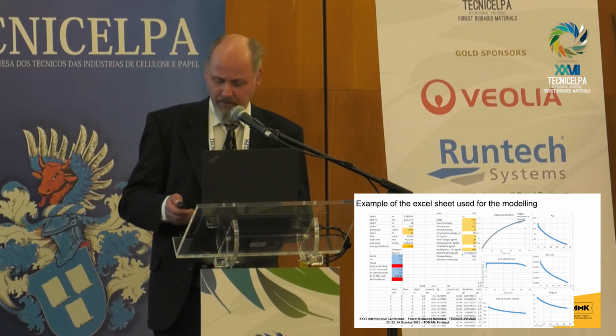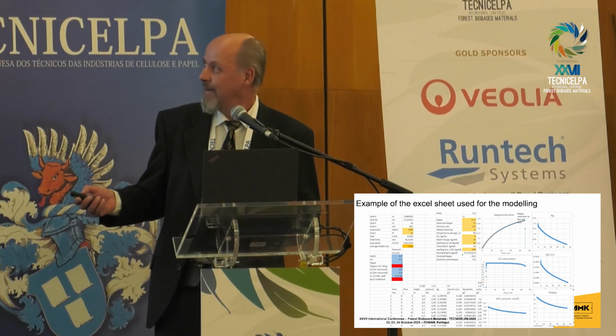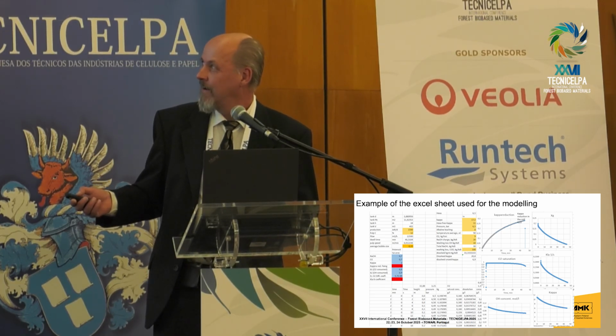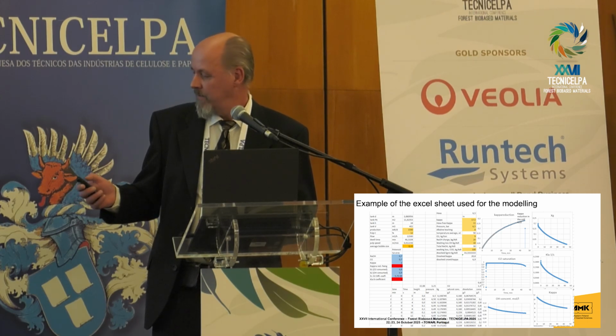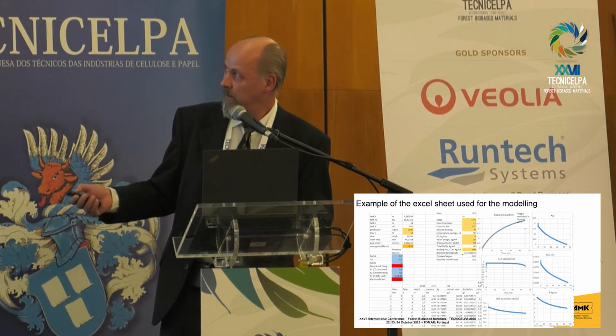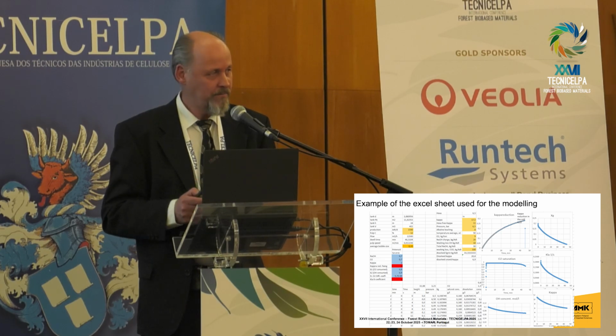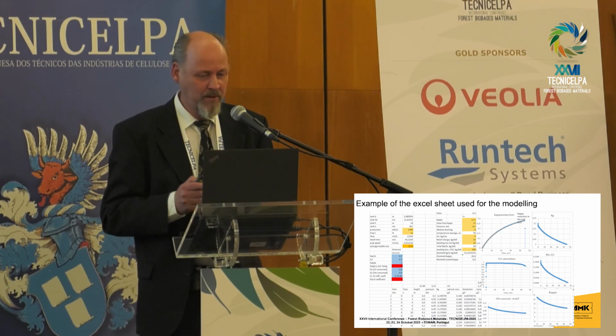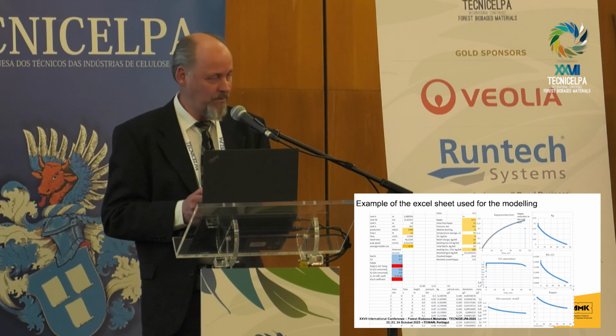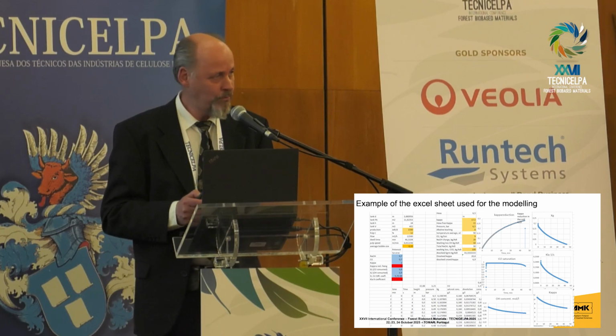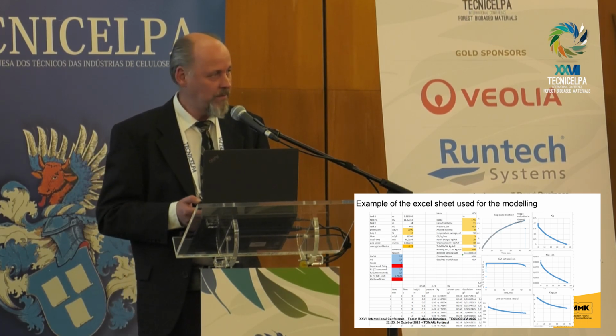One most important thing here is this saturation level of oxygen in the reactor. So what does this mean? It means that at a certain pressure and certain temperature, there is a certain maximum amount of oxygen which can be dissolved. And now we can calculate this saturation level, that is, how close we are to this maximum amount of dissolved oxygen. If the number is 1, then the process is totally saturated.